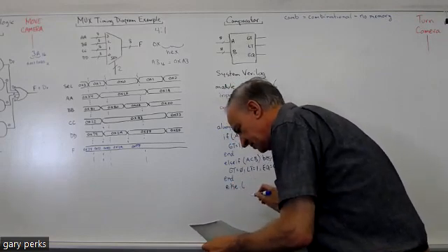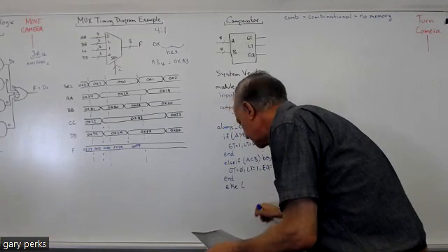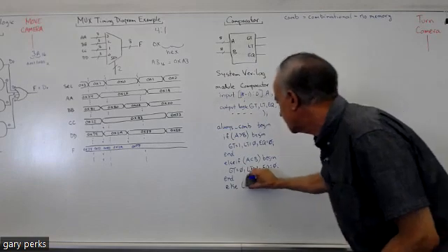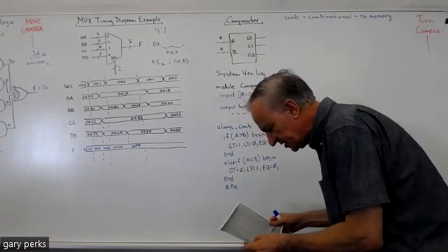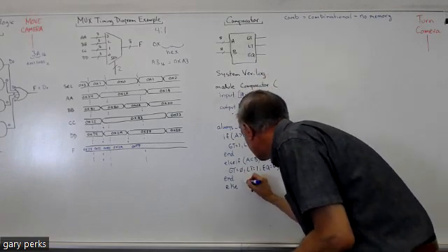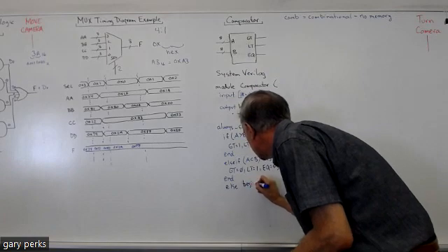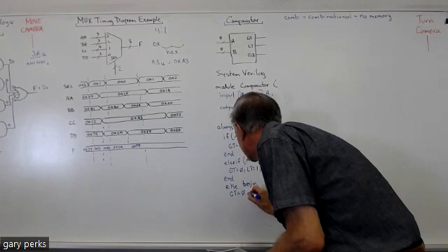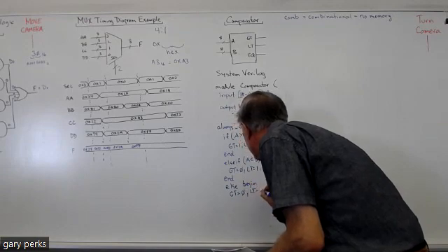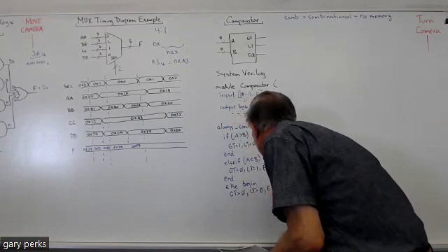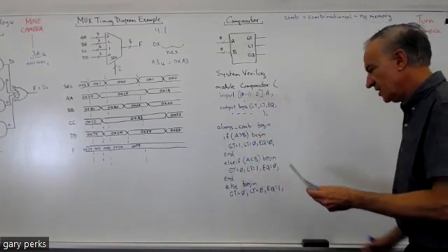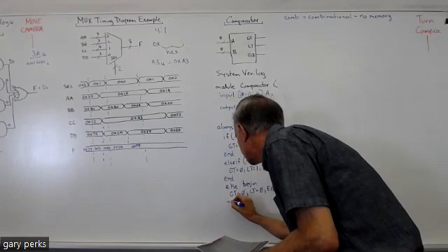We don't need A equal, because it would have to be that, right? If it's not less than or greater than. So we just have else and then begin. And then we would have GT equal to 0, LT equal to 0, EQ equal to 1 semicolon. And then we have to end this begin.